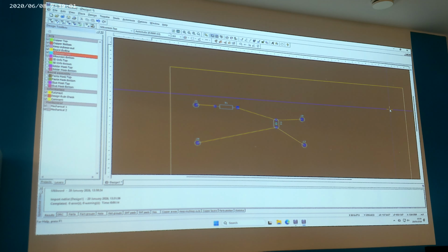Okay, I have got what is on that board. The connectivity, you can see it, it's the same as that, isn't it? Two input pins, two output pins. From the top pin I've got the resistor going to the capacitor. Where the resistor and capacitor meet, I've got that going to the output pin. And I've got the two ground pins connected to the other side of the capacitor. Can you see that? Does that make sense? If not, carry on playing, it will make sense.